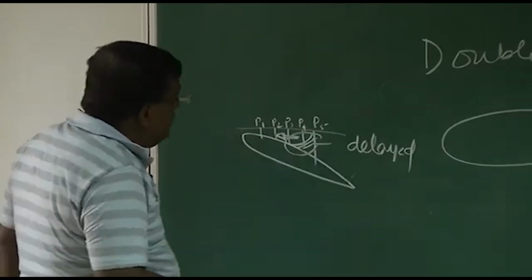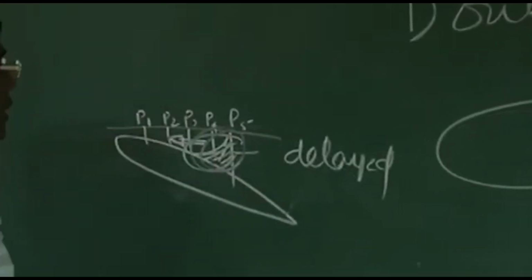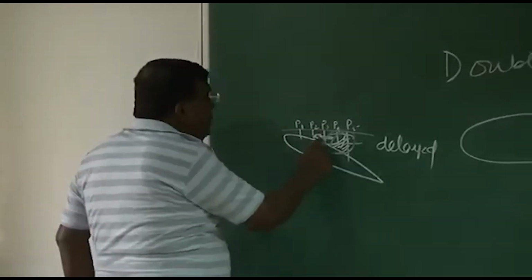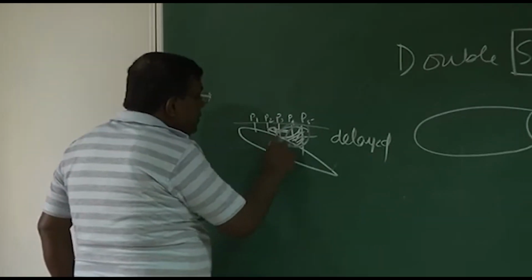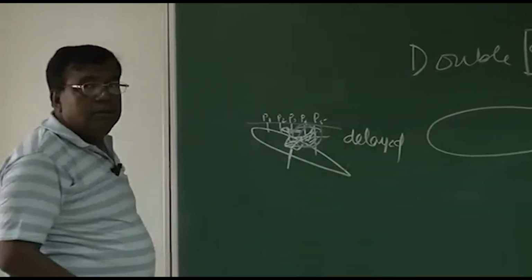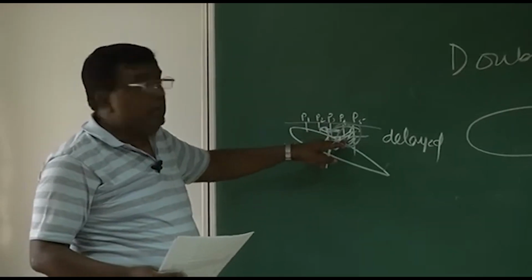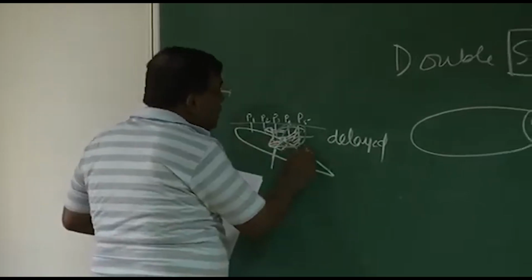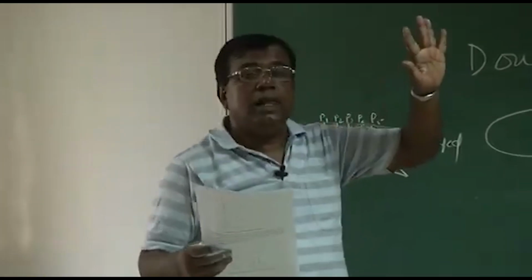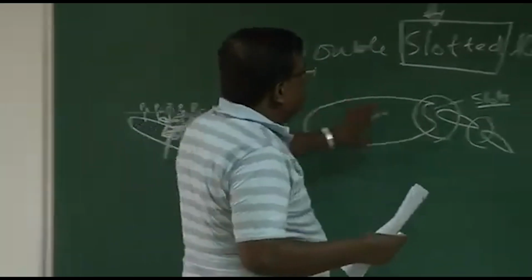By simple common sense, what does it mean to us? If this friend of ours, the boundary layer, is having a deficit of energy, I supply him energy. So what do I do? This is some fluid with high energy, I pump into this area. That energy will revitalize this fluid particle, and this separation point from here may come here. Effectively, I can further increase this angle. Is this clear? Now, with this understanding, come back here.